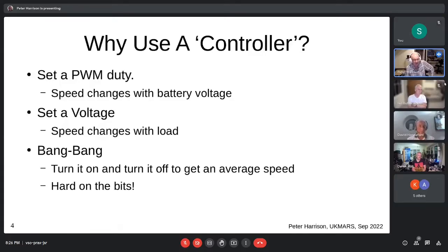If you want to drive the whole thing at a constant speed, you might, and I've seen it done, just say, it's going too fast, I'll stop driving it. It's going too slow, I'll start driving it. In fact, I used to work with somebody who operated their car that way. It was most disturbing. That's called bang bang control, and it works not terribly well, and it'll wreak havoc. Your gearbox will be slammed in forward and then slammed on the brakes and then slammed forward again and so on. But it'll work. It turns out, though, that we can do better.